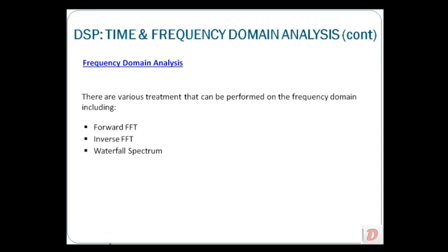And the waterfall spectrum is another one of our spectrums, just that the way it is plotted is cascaded. So you have spectrums plotted over a series of times, in 1 second, 2 seconds, 3 seconds. Maybe every 2 seconds it plots a spectrum. From there you can see the change of your vibration amplitudes in terms of different frequencies over time. So you have this waterfall spectrum,